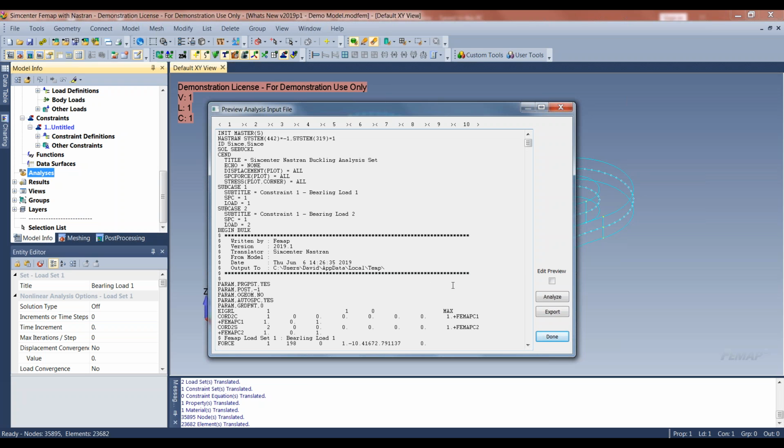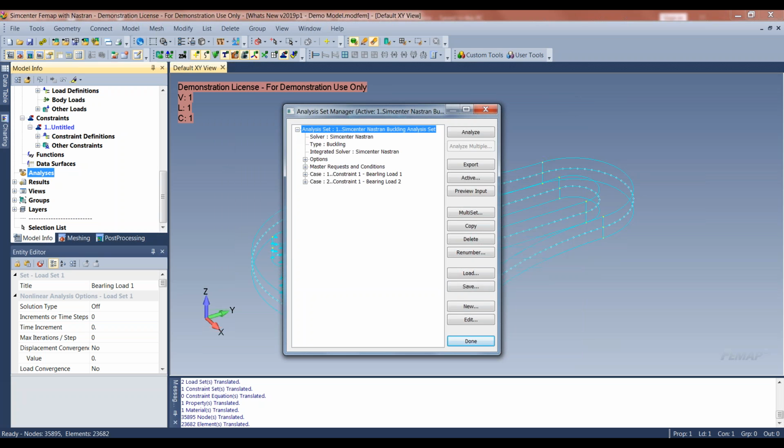But the reason this came about is because they've added a lot more capability to manually control and define and set up stat subcases, which can be used for preload, for buckling, and then in the more advanced solution sequences like the new multi-step nonlinear solution 401 and solution 402, which is the nonlinear kinematic solution sequences. You can do things like nonlinear pre-stiffening, and basically those stat subs have a lot of use cases within those solutions.